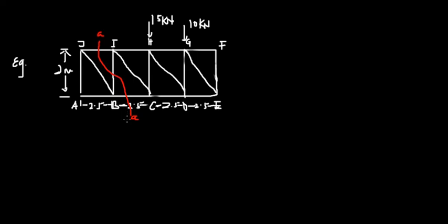That's where we introduce our free body diagram. That's where the free body diagram is. And then we have certain reactions over here. This reaction at point A, and then another reaction at point E. So we have to calculate the forces within J, I, B, C. So the main point is to calculate the forces within the section which has been cut.